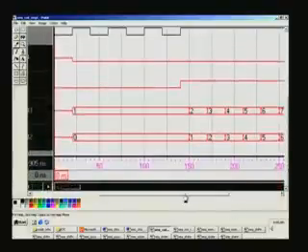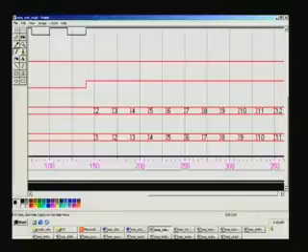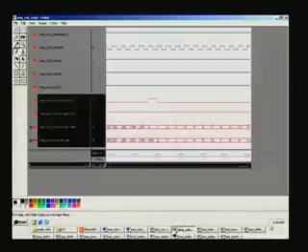And you can see the counting progressing smoothly by 1 at every clock pulse. If you have a look, there will be a clock pulse here, a rising edge of the clock pulse here, and once again it will rise here. So, again you can see at all points of time this counter next is pre-incremented here, and going to the next waveform, which is a continuation of this, we will have.